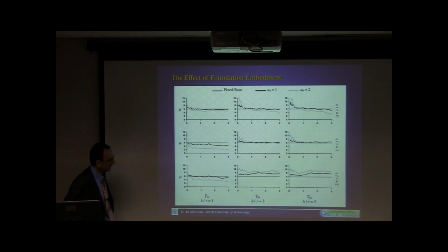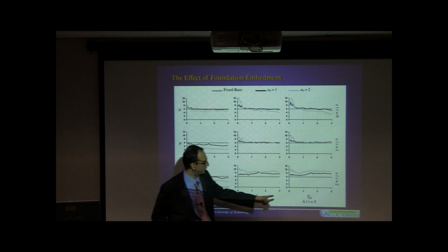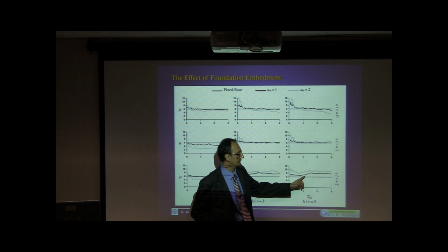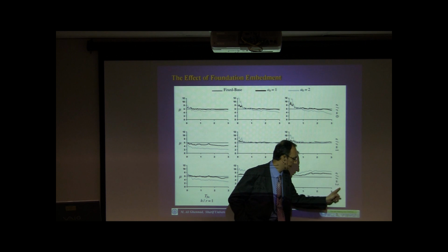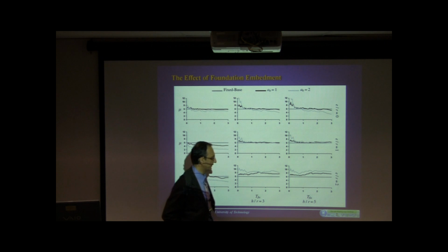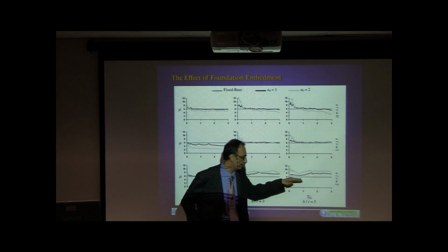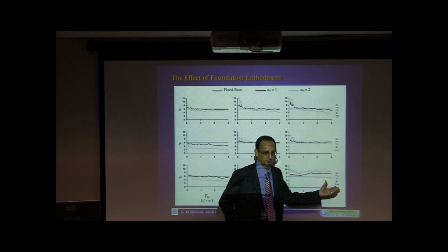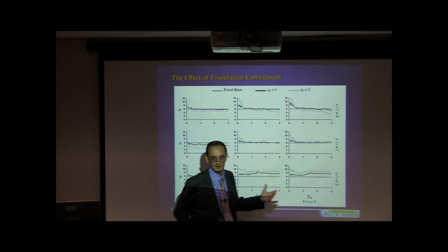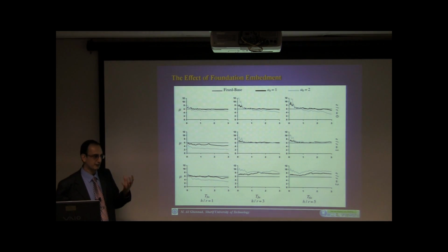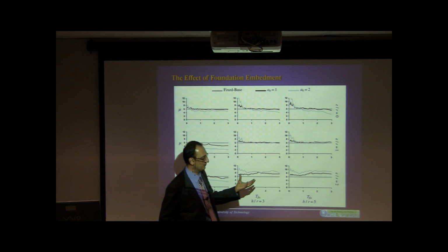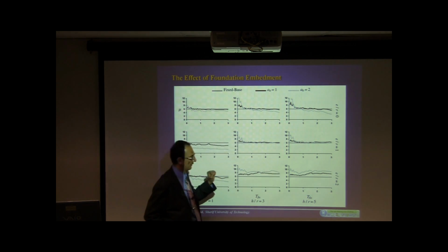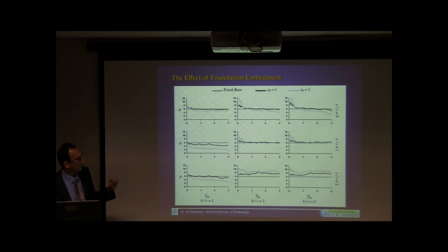And it can be seen that for the case of slender structures, the ductility demand for deeply embedded foundations can be higher than the ductility demand for the fixed base structure, which has been set to 6 here. Of course, E over R equals 2 is a large value. But we want to talk about the extremes and the phenomenon that for the case of embedded foundations, the rocking input motion can play an important role. Of course, it has been known for many years.